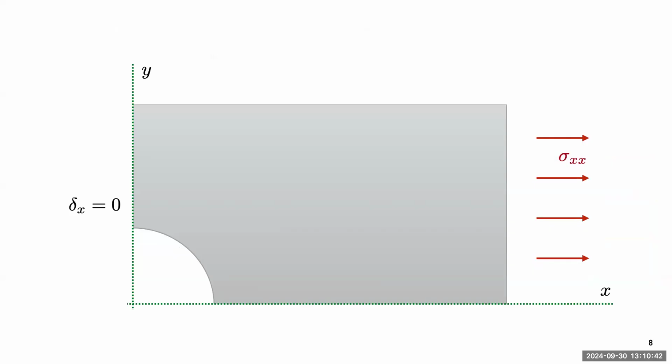0. So to put that in a different way, if you're a piece of material or a node on a symmetry plane, you have to stay on a symmetry plane. So if you moved off the symmetry plane, the problem is no longer symmetric. So if you have a symmetry plane, you have a piece of material. If that piece of material moves to the right, then you can't have it also on the left as a reflection. That would break symmetry. So for any material that's on a symmetry plane, it has to stay on a symmetry plane. Otherwise, the problem's not symmetric and it's invalid.